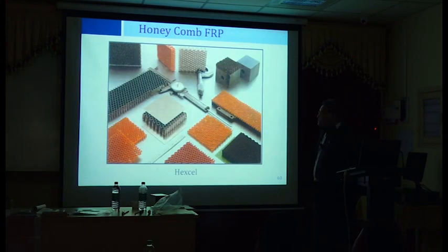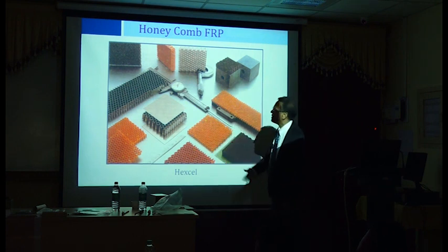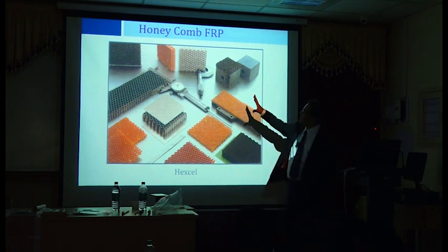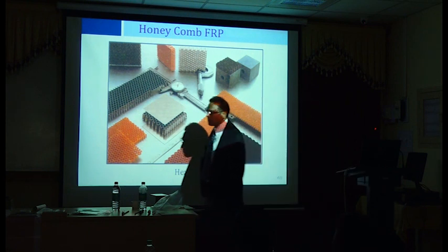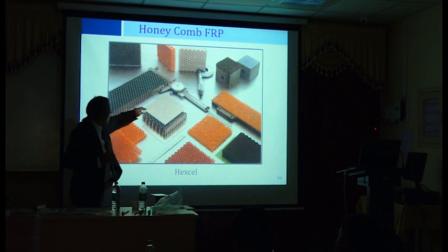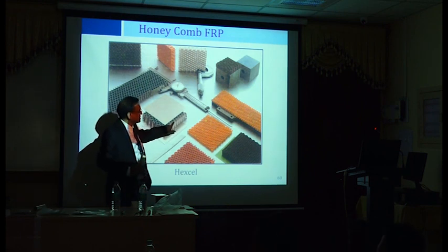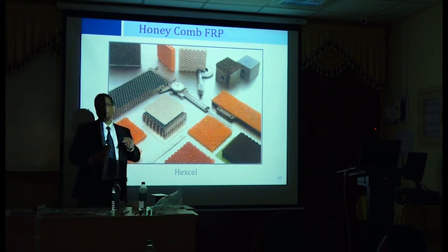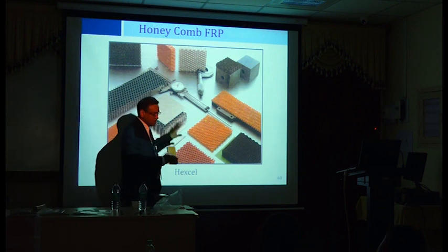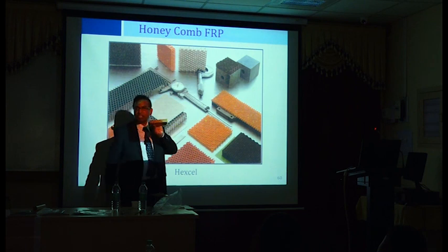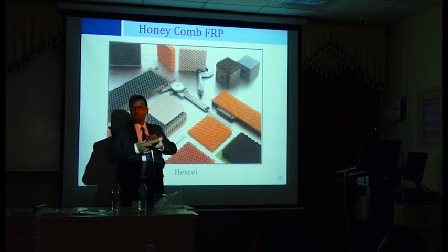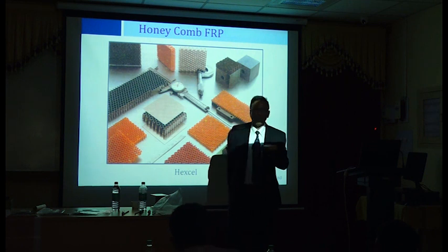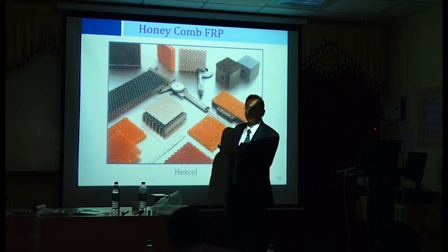And of course, there are new types of, not new anymore. 15, 20 years back it was new, but not new anymore. This is a honeycomb construction or honeycomb structure. So I have a sample of this also. So they place one plate on the top, one plate at the bottom, and you have this so-called honeycomb formation. And then you fill it with foam, structural foam though, not normal foam, structural foam. So the foam and the ribs will take the shear loading, and the top plate and the bottom plate will take the flexural loading. So they use this in some of the aircraft structures, as floor panels. And it's so light, you can see it's very, very light.